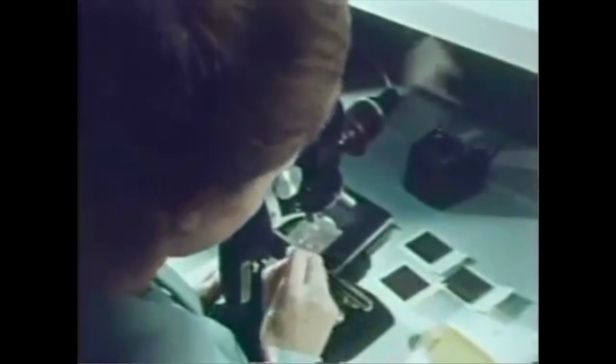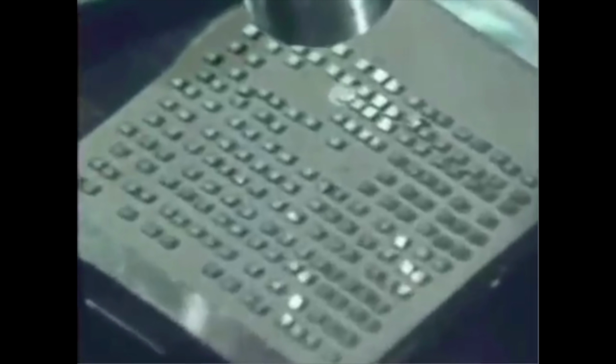We then scribe the wafer using a diamond point in the scribing machine. After separating, cleaning, and drying the integrated circuits, we fish out the ones that are bad. If we have been successful to this point, we have a high yield of good ones. From this point on, we are going to package the circuits, and so whenever we throw one away, we're going to throw away a complete package.